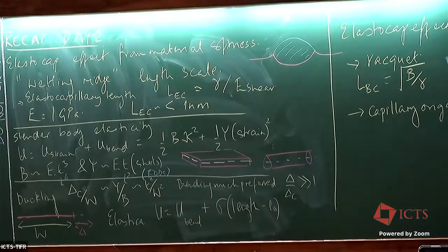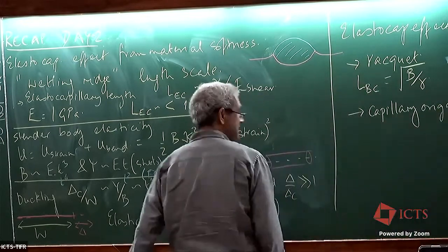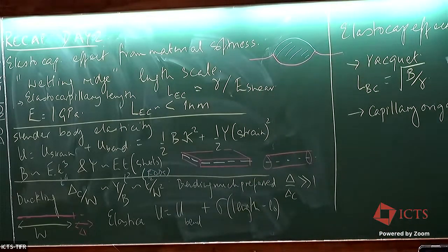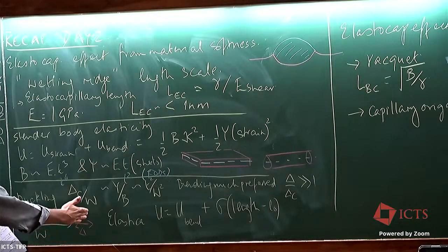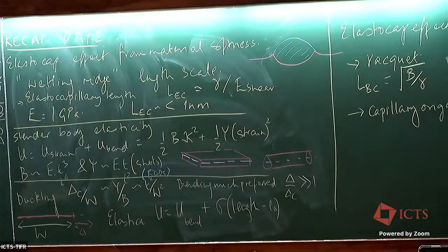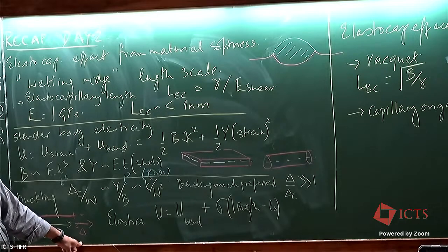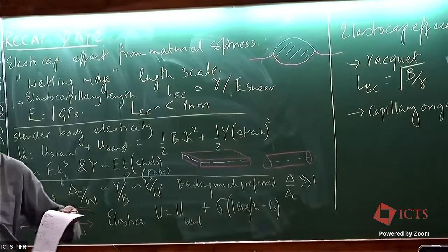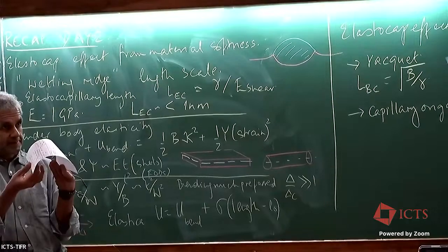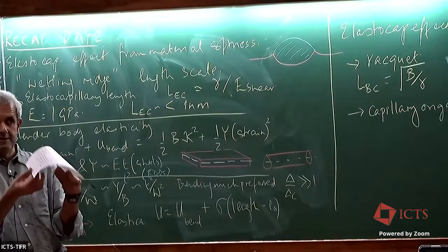All right, just to get some feeling for how thin materials behave, we spent another 10-ish minutes thinking about the simplest possible buckling experiment. You take a sheet or a rod, I only draw its midplane, and I push it this way. And we ask, at what value of displacement does the energy stored in compressing this... It can react by completely compressing, or it can react by going out of plane and not changing its length, or anything in between.